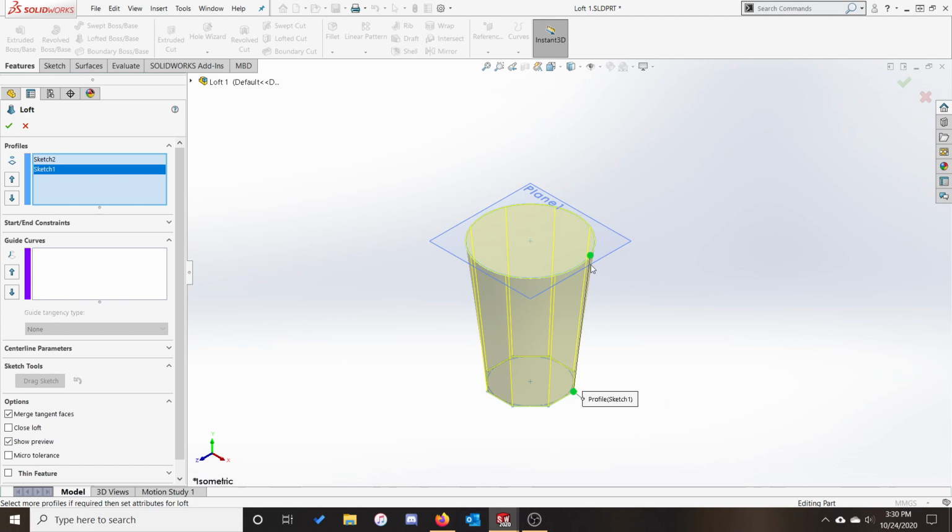We get these guidelines to help us determine how the loft moves. We can alter the shape by left-click dragging on these points. This process twists the intermediary profiles. Sometimes your model starts twisted, and it can be a pain to snap these guidelines into the correct position. For that, let's go over the rules that SolidWorks uses to define these guidelines.